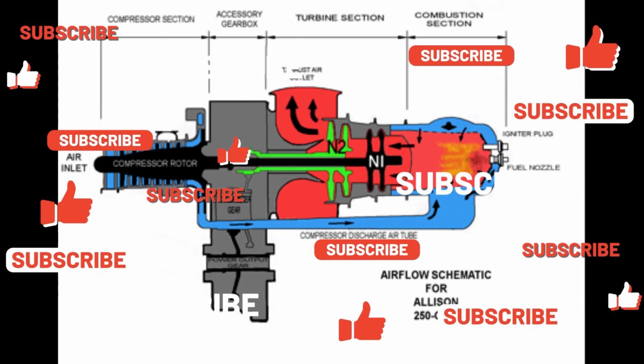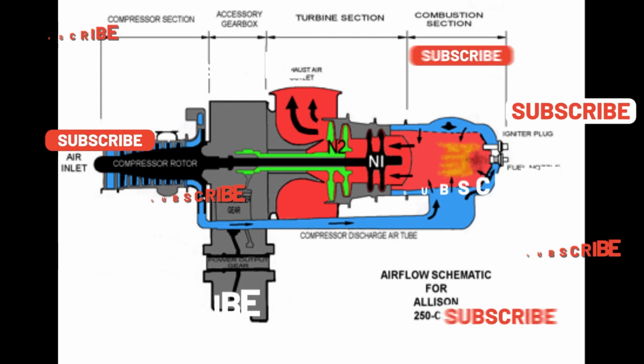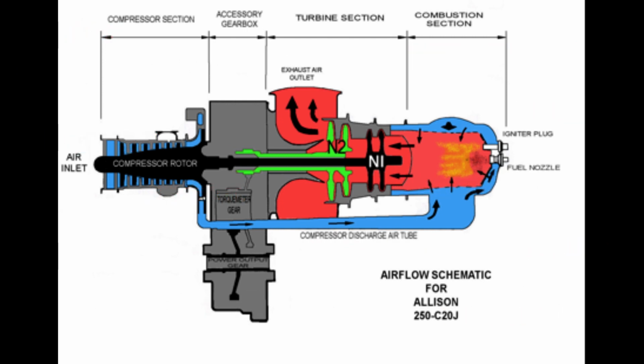The gas turbine engine mounted on most helicopters is made up of a compressor, combustion chamber, turbine, and accessory gearbox assembly. The compressor draws filtered air into the plenum chamber and compresses it. Common type filters are centrifugal swirl tubes where debris is ejected outward and blown overboard prior to entering the compressor, or engine barrier filters (EBF), similar to the can-end filter element used in automotive applications.